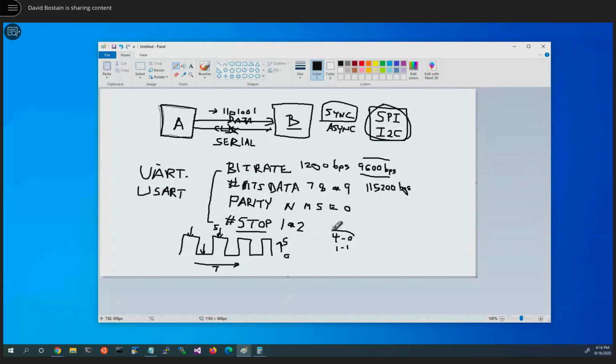What I sampled must have been a 0. So if the number I see is 3 or more, I will vote for that particular bit to say that's what I think I got, even though I might get 1 or 2 bits that are wrong. Now, the higher the number, the stronger chance it really was a 0 or a 1.